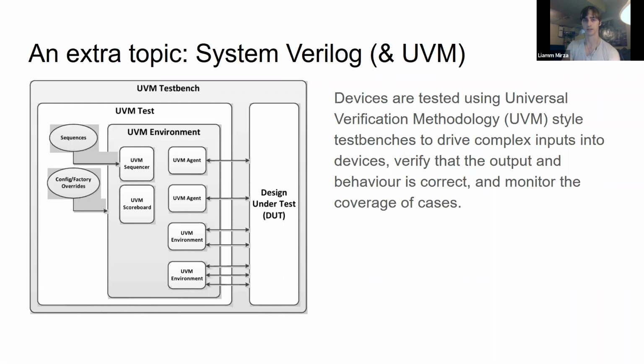So it's stuff like whether every bit has been set to 1 or 0, or every register transition combination has been achieved. It doesn't necessarily have to be every single one. You can waive certain cases if they're deemed non-relevant.